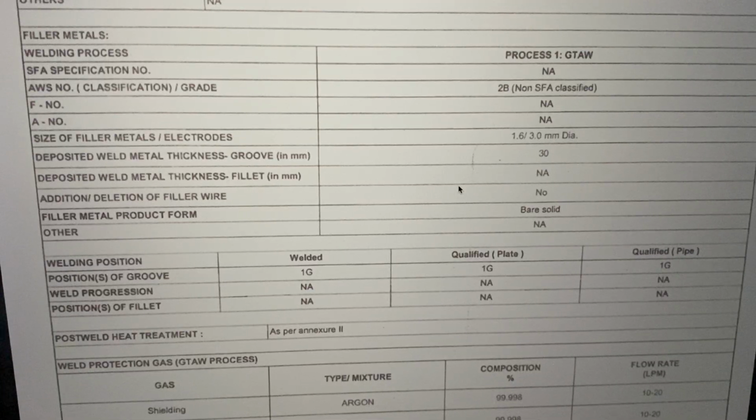Now what is F number? F number is purely the metallurgy of the consumable we are using, or the resultant metallurgy which you are going to get in the weld. But A number is different. Even though I said the resultant weld is covered in F, it is undiluted. That means when we have a build-up on a plate, after the 7th or 8th layer, the properties or the chemistry are checked for calculating the F number. But in reality, we cannot deposit so many runs, and there will be dilution from both sides of the parent metal. So the resultant chemistry is classified into A number. So there is a slight difference.